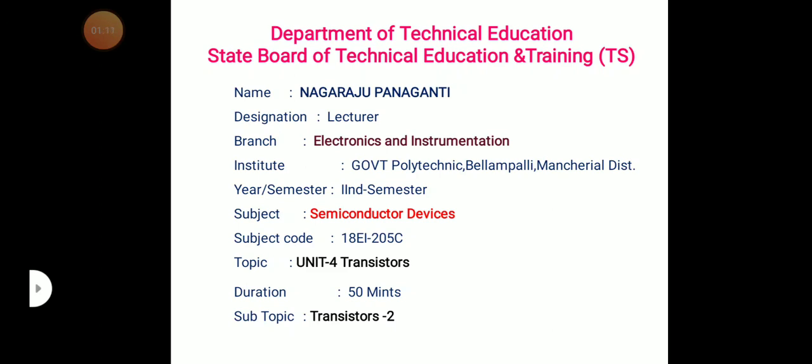Emitter is highly doped and the size is moderate. Coming to the base, it is lightly doped and the size is very thin, and collector is moderately doped and its size is bigger than the emitter comparatively. So these are the three terminals. We applied the biasing, that is called active biasing.